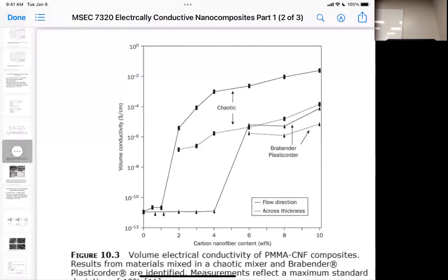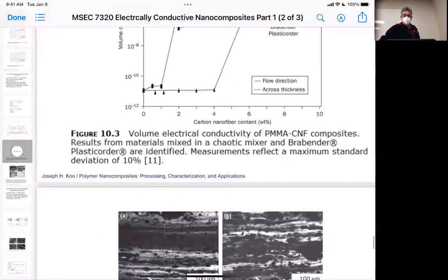In the other system, we have started right here at 1, we're getting our percolation threshold and a higher conductivity. But now look, we have a different transverse conductivity. So that's telling me we're having order in the direction of flow, allowing us to have more pathways in the direction of flow, fewer going off in the other directions. Okay, so gosh, you've got to take a couple SEMs of this.